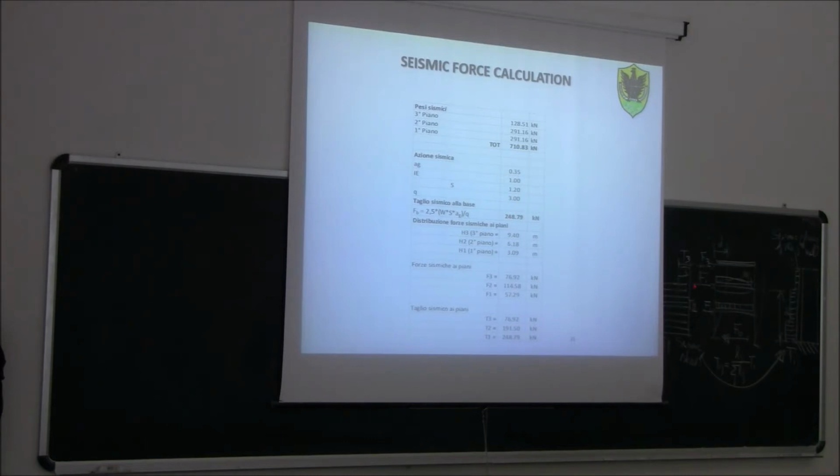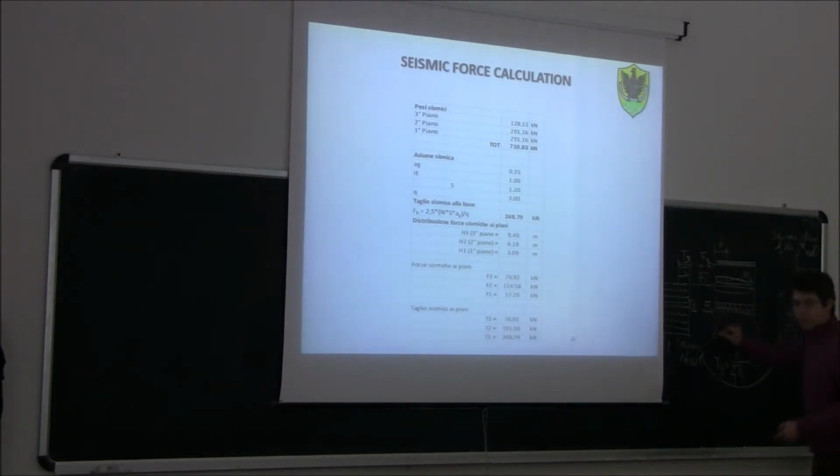But the seismic forces, you can see, are not constant, because this mass here, which is the same as here, is higher. The shear is not constant. It's just constant between this section and this section. But once you move above the floor, it changes. You see, there is a discontinuity here, the same here and here. Discontinuity, and then discontinuity. No, because it was hidden.